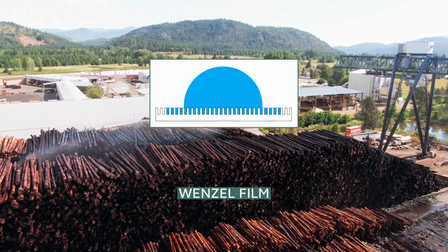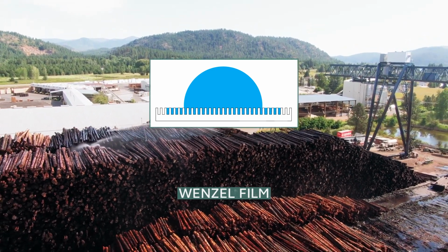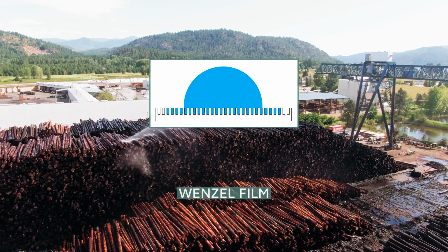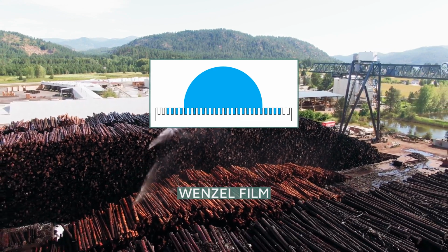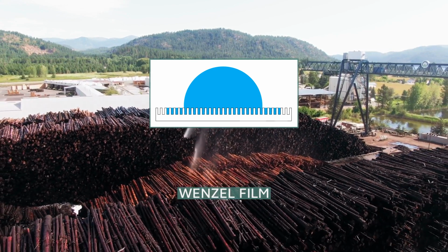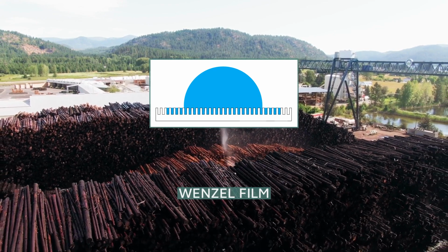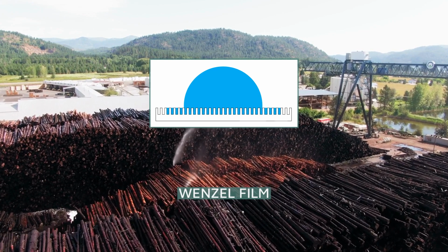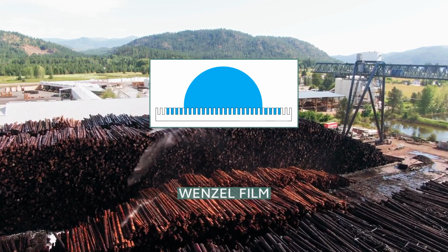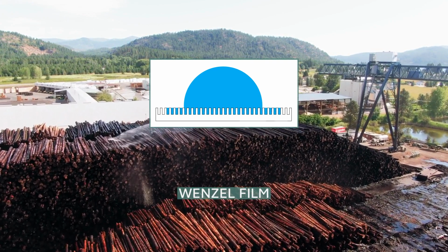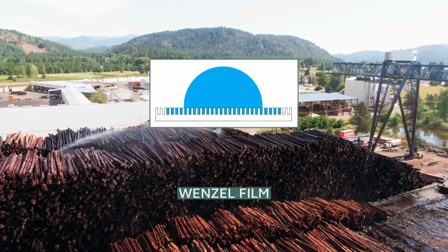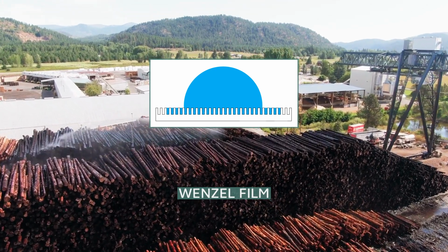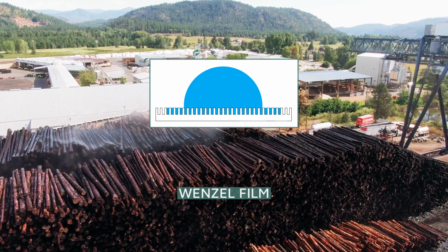The penetration front propagates to minimize the surface energy until it reaches the edges of the drop, thus arriving at the Wenzel state. Since the solid can be considered an absorptive material due to its surface roughness, this phenomenon of spreading and imbibition is called hemiwicking. The contact angles at which spreading/imbibition occurs are between 0 and π/2. The Wenzel model is valid between θc and π/2.